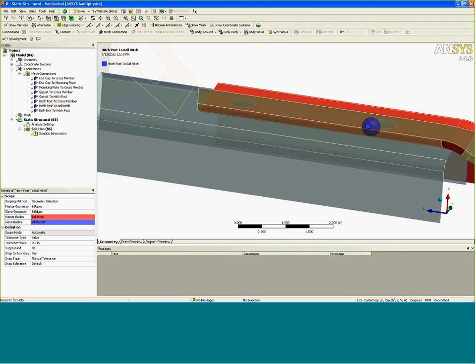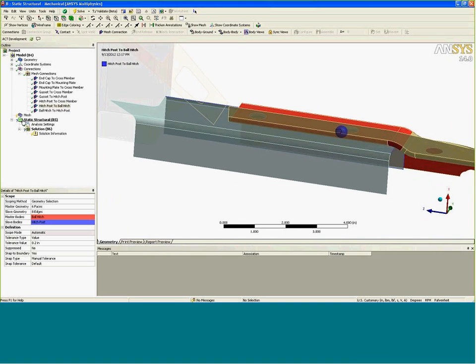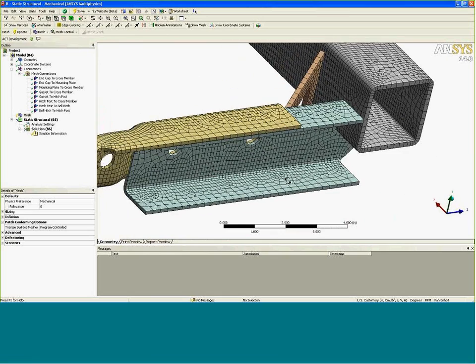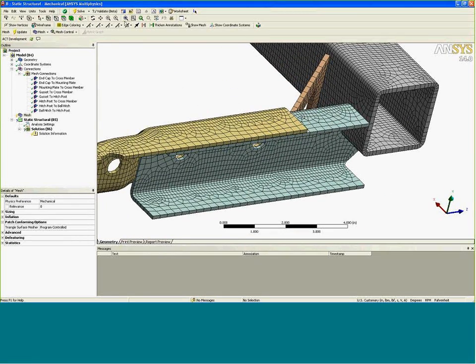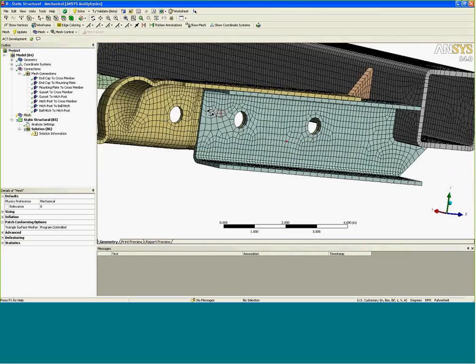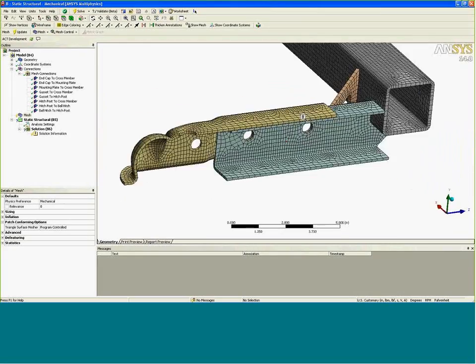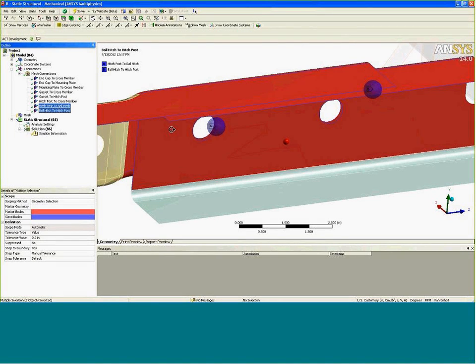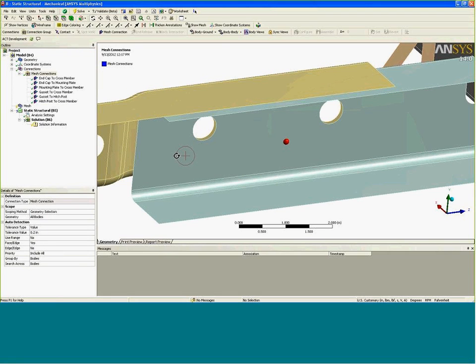So options here. If I show the mesh for a second, you can see that it would really be if these surfaces were allowed to interact with each other. And we want to have a mesh connection between any of these bodies in here because there might be some slow bonding. So these connections that are these two in here, I'm just going to delete them because I'm going to connect that up. So for interaction between these surfaces, we can just put in a contact to handle that.